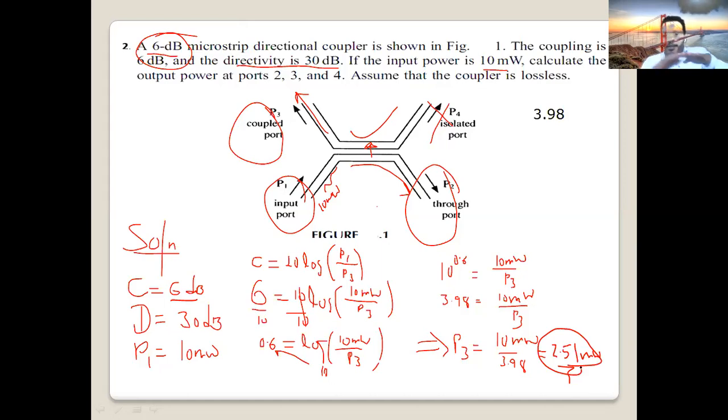Similarly here, by using a directional coupler, transmission is still going on, but we can take a small sample from the signal and analyze it using a power meter or spectrum analyzer. You can determine your frequency, measure power, and check whether there is any interference. Is our signal okay, or is there any noise? To do this checking, we need to take a sample.